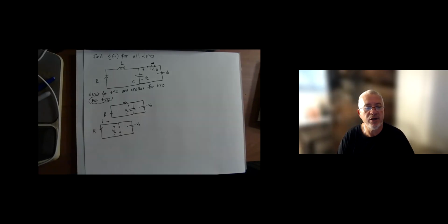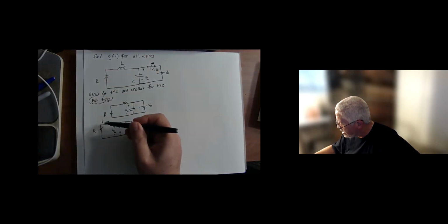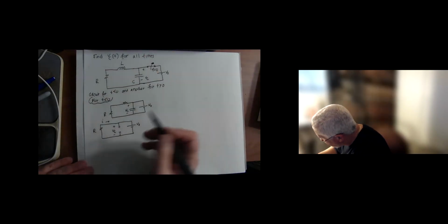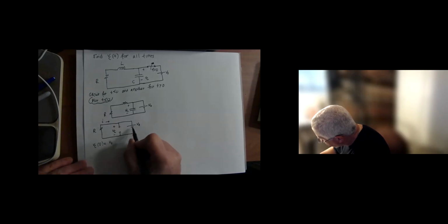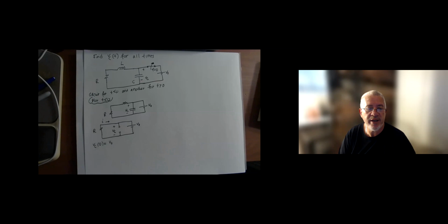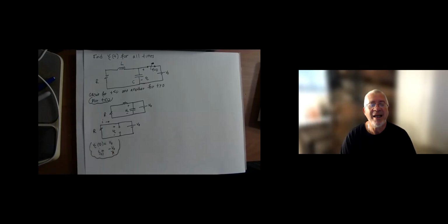And then we need the current also on the inductor because that's going to be our initial condition. Okay, so we need the capacitor voltage, but that was asked. But we also need the inductor current here. And these are fairly simple. The capacitor voltage, clearly VC at 0 is V naught. It's just parallel with the battery here. Okay, so that's V naught. And of course, the inductor current is minus V naught divided by R. So these are our initial conditions, and I should put I at 0. These are our initial conditions right there for t less than 0.